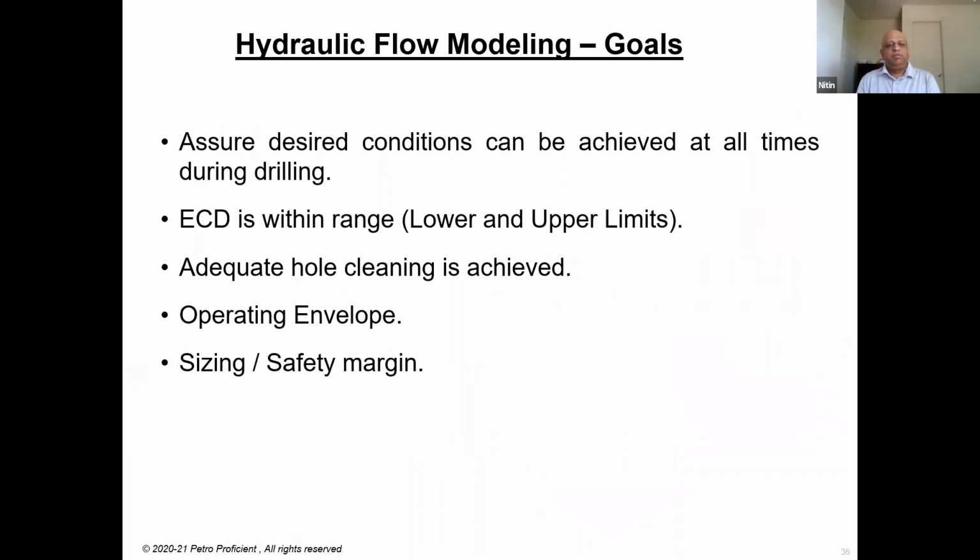Now, the goals of hydraulic simulation, hydraulic modeling, are basically to ascertain that we have the desired conditions while drilling at all times. ECD is within the range. You have your right ECD available. ECD is basically that hole cleaning is adequate, and you are within your operating window. And you would get the right size of equipment that is required to pump the right volume of air and liquids and other chemicals required. And you have the safety margin maintained.